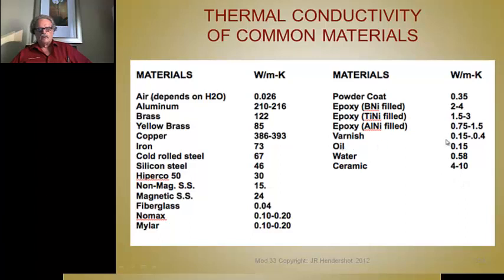Ceramics are pretty good. Oils aren't that great. Varnish is very poor. Epoxies that are filled with aluminum nitride are pretty decent. Epoxies filled with titanium nitride are pretty good. Epoxies filled with boron nitride are quite good. Now powder coating, epoxy powder coatings used for stator cores, that we saw in some earlier lectures, those aren't bad, but they're sure not great.